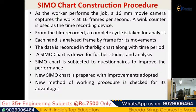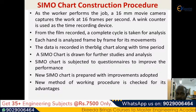From the recorded video, we are going to analyze what cycle is being done, how each and every hand is moving, how each and every limb is moving, everything. Then you are going to assemble everything inside a SIMO chart by use of therblig symbols. So what I have said is that it's a micro motion study. For micro motion, you have a time period of 1 by 2000 of a minute, which can be recorded by a 16 mm movie camera. With that camera, you can analyze for each and every wink how your limbs are moving.